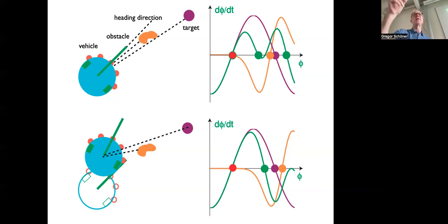And the attractors, yes, and actually in the subsymbolic approach, I'll show you the formula, so it really falls off with distance, and that actually means that there is, over time, a rebalancing. That is, when you're far from obstacles, then the target is the dominant term. And when you're close to obstacles, then the obstacles become dominant. And that's the only chance how you can approach a target where there's some obstacles before. So you go in this general direction. And when you're close, then you're actually figuring out where there might be an opening to go around.